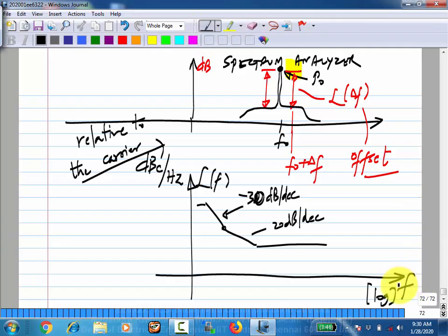Sometimes, this is again convention, the notation is not always consistent. Sometimes you use delta F here, sometimes you use F. But this is the spectrum of the phase itself. But you don't see the phase directly, right? You see a periodic signal which has this phase. So each spectrum will have this spectrum translated to F0. So all the frequencies here get translated to F0. Is this fine? Any questions?